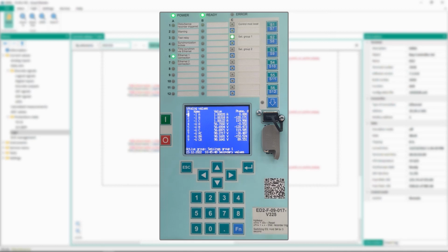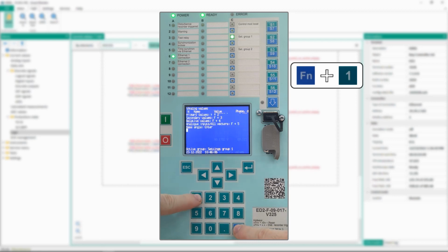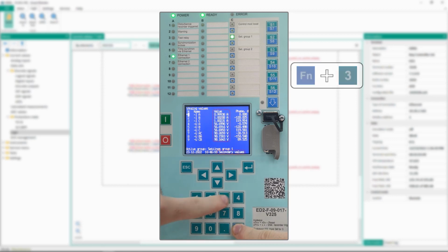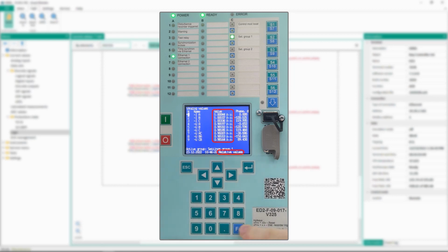Navigation and change of data display modes in all menu items discussed below will be carried out using arrows and key combinations. The list of available combinations for each window can be viewed in the Help window by opening it with the F and 1 key combination. For example, to change the display of analog signals, we use the following key combinations: F and 2 to display primary values, F and 3 to display secondary values, and F and 4 to display values in relative units.